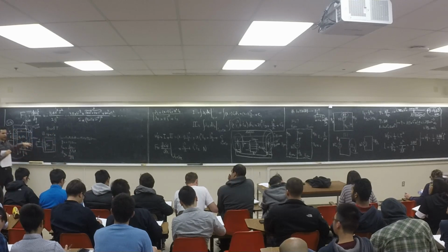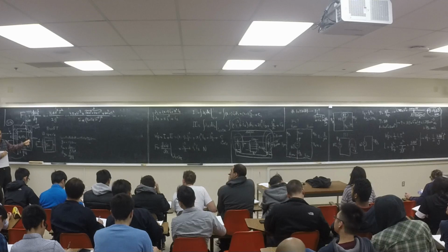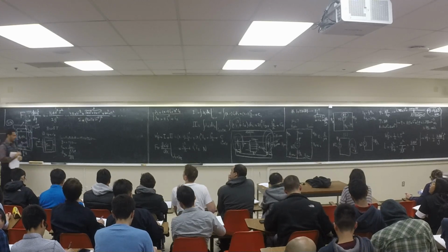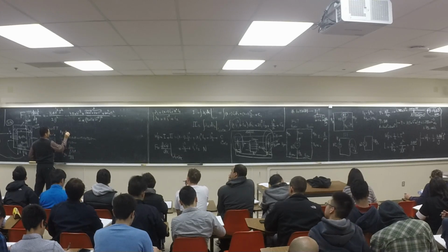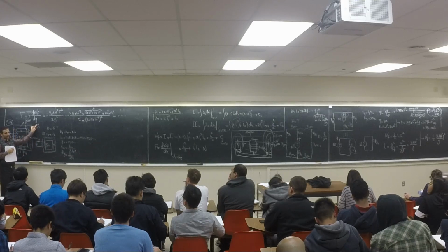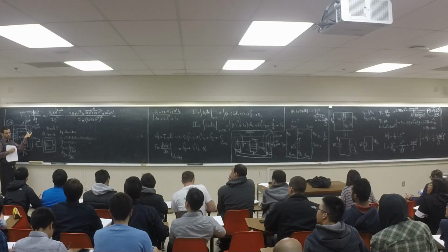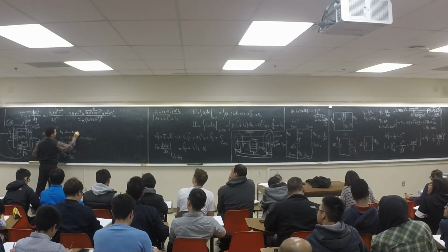In this case, it didn't say anything about fringing flux, so there is no fringing flux. Basically, AG and AM are the same, right? How much is AG, AM? Depth is 2 centimeters, right? And here is also how much? 2 centimeters. So 2 by 2, it's going to be 4.